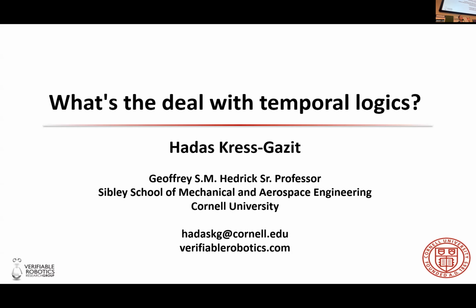It's not that they're not as nice, but LTL and STL also have trade-offs. So LTL I can synthesize ahead of time, and I know ahead of time whether I can perform the task or not if the abstraction is accurate. STL typically is an optimization problem that's done on the fly, so it's hard to give guarantees. There are some ways to give guarantees over a finite horizon. You can provide a little bit less guarantees a priori, but they capture different aspects of robotics, in the sense that STL is better for leaning into the continuous, versus LTL gives you a little more guarantees.